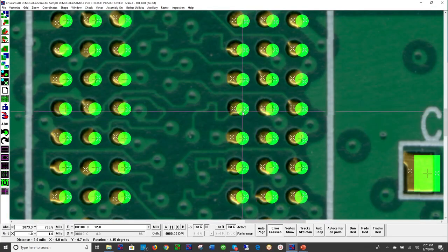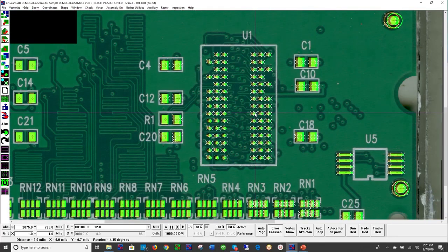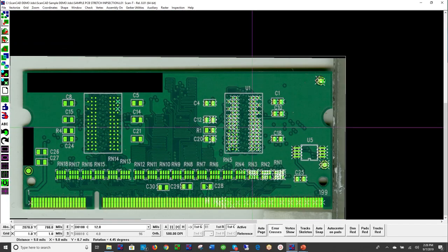If you use this green data to manufacture a stencil, to print conductive material onto these gold pads right here, you can see we would have a very serious production problem. We'll talk more about that in a minute with a Motorola study that was done with this technology. So I just wanted to give you a quick example of what that inspection might look like.